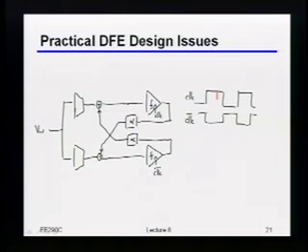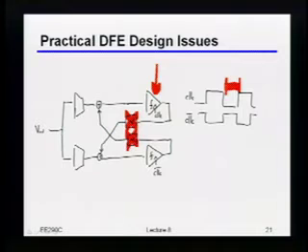Wait, what does this buy us again? Okay, so in this particular example, it turns out to not buy you anything, which is kind of why I did it this way. But imagine that I wasn't closing the first tap, right? So if I didn't need to do this, then now notice my comparator actually has twice as much time to reset itself, right? And in principle, if I was really limited by, let's say it was a CML comparator or something like that, I've also got twice as much time that I'm staying in the input sampling phase. Of course, right? Not closing the first tap, meaning unrolling the first.